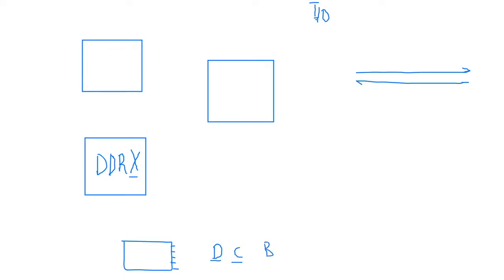Now we all know that D and B share the digital IOs, while C mostly takes the analog pins. So you have A0 to A5. So if you were doing analog read, it would be port C that you'll be accessing. So this is quite important. If you are doing your assignment, please remember.